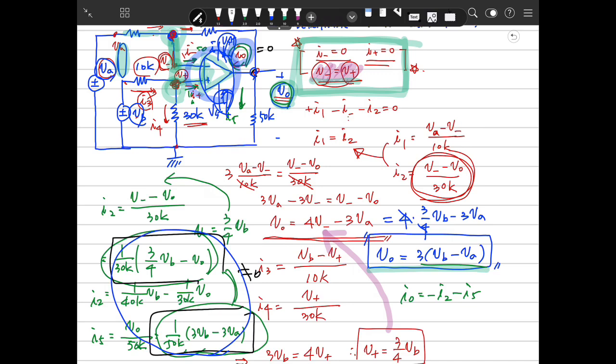If you have an op-amp circuit, then you should write the relationship between the pin current and voltage. Next, make a node equation based on the input node. And remember, you should not make a KCL at the output, because at the output node you cannot use KCL.